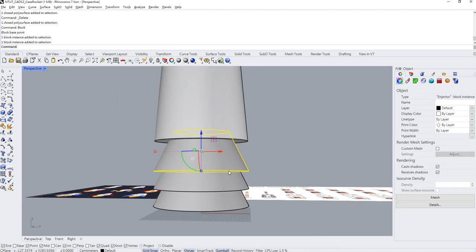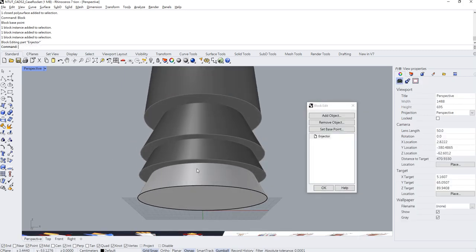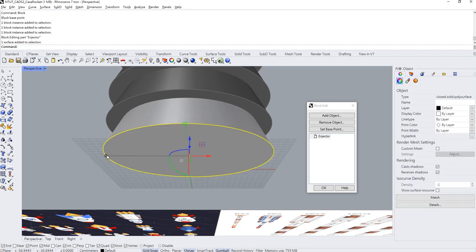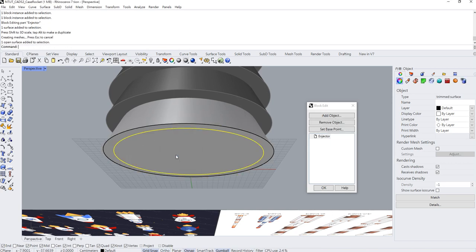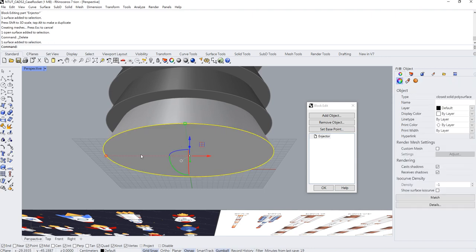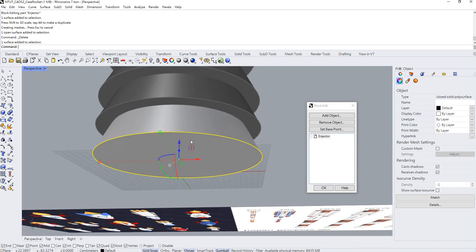Alright, so now the only thing I have to do is add one thing and all the rest will change. So very simple, just like what we did before. Let's hold on Shift and Control key and make this one smaller. Hold on Shift and Alt key. Copy one more. And for this time, oh, sorry for that. Let's delete. Let's do that again. Select this face and hold on the Shift key. Sorry. Using extrusion to extrude. So let's select the little blue dot, extrude.